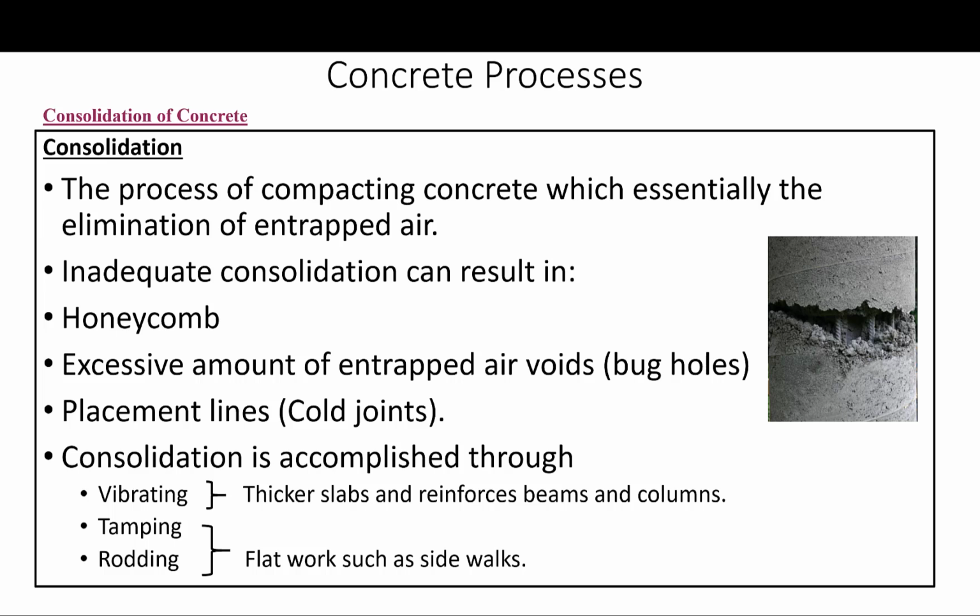Consolidation can be achieved basically by vibration. This is typically in thicker slabs and reinforced beams and columns where it's congested, so vibration is essential here. Tamping and rodding, this is for flat work such as sidewalks that is not congested like beams and columns.